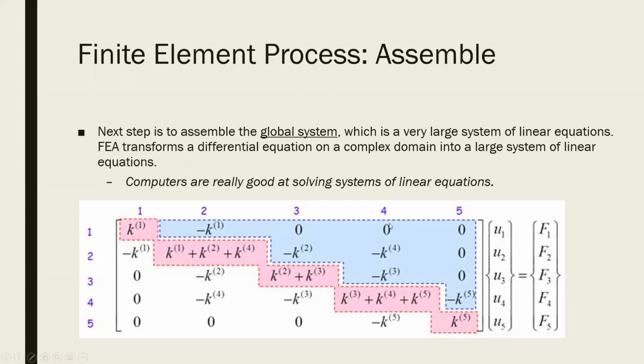Okay. And so, when we do finite elements, this is what it's doing underneath the hood. ANSYS is doing this under the hood, but it's an important step. The reason we do this is that the funny thing with computers is that they're actually really bad at solving differential equations, but they're really, really good at linear algebra. So the goal with finite elements is that if we can take a really complicated system governed by differential equations and turn it into a linear algebra problem, then the computer can solve it just like that. A lot of the theory that we're going to learn in finite elements is how do we take really complicated situations and turn them into a system of linear equations? Because once we get it to that point, then the computer can take it from there.